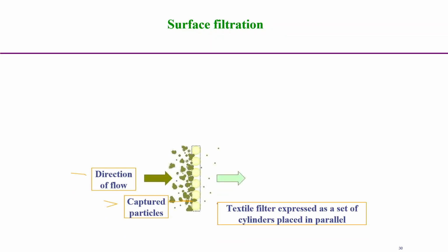Now, next is the depth filtration. Before that, we just try to see how the cake is forming. In the direction of air flow, air is flowing and small particles are going to the other side. The filter will initially start capturing the larger particles, then when the cake starts forming, it will start capturing the smaller particles also.